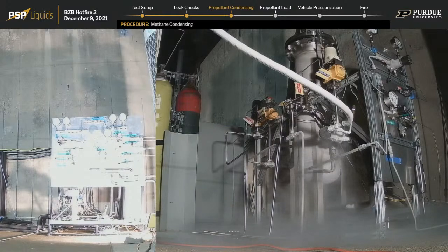Looping back to your earlier comment, Boomie Zoomie 1 had 2 successful hot fires, and it was determined that Boomie Zoomie 1 cannot meet the stay and altitude requirements. One of the major reasons for this was A, undersizing the propellant tanks based on what was needed, and B, undersizing the helium system.